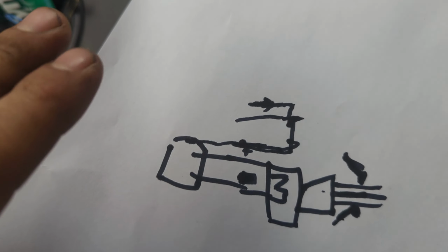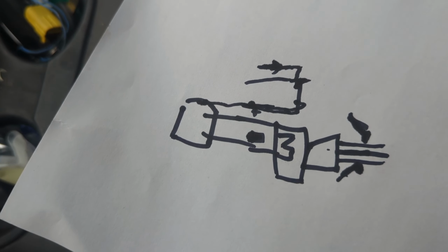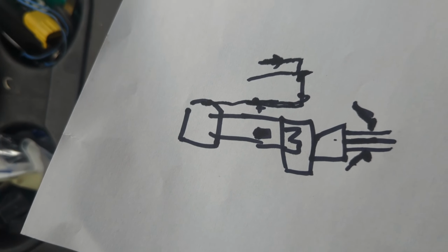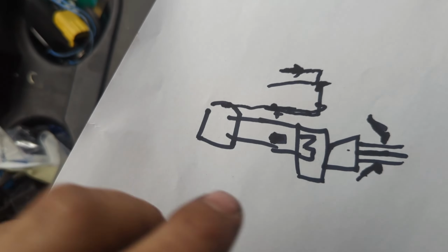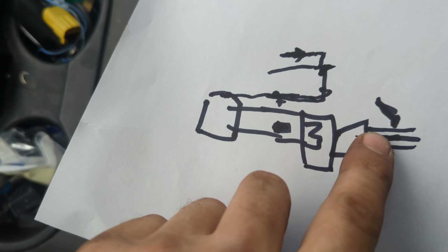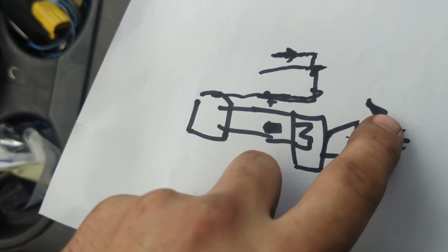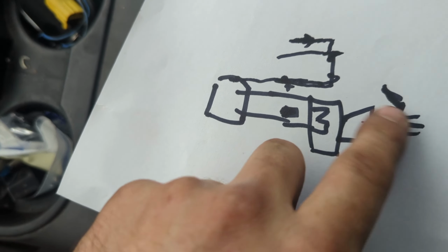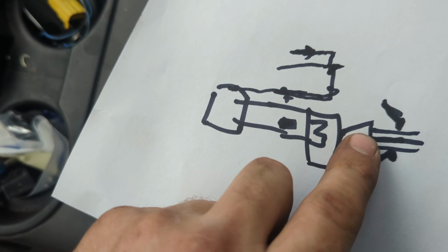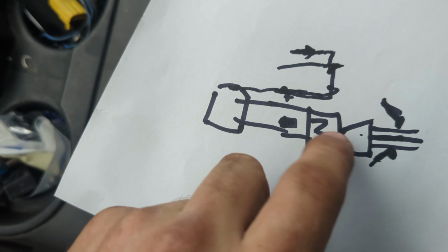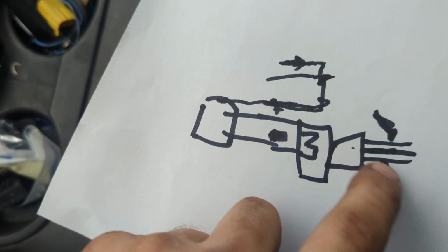What ends up happening at this point is that you will not have full voltage to all the high current modules, because there isn't really a direct connection. It's only going to be connected through these terminals over here. So this guy's going to be connected over here even though it's locked. This terminal right here is going to be pushed back and connected over here instead of directly connected to the battery plus terminal. So there's going to be a voltage drop.